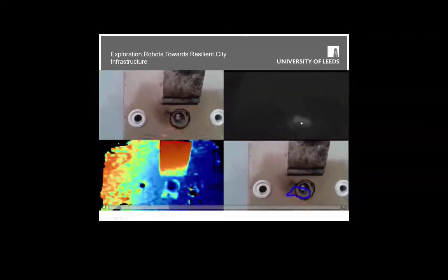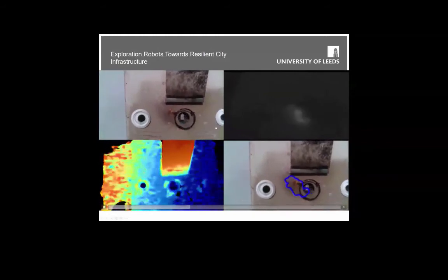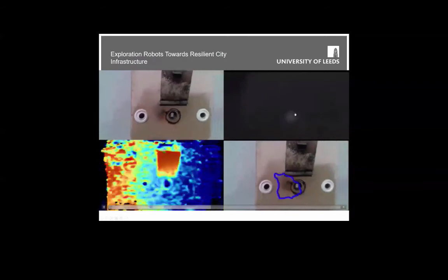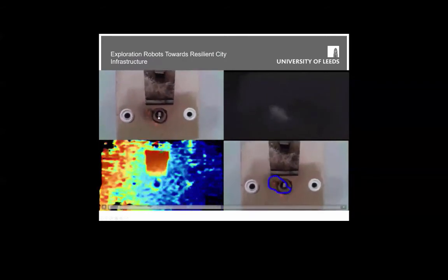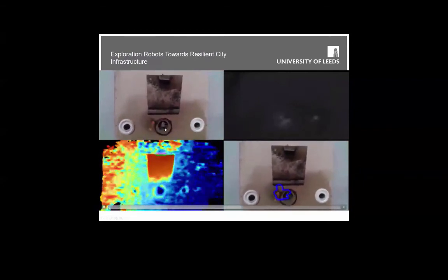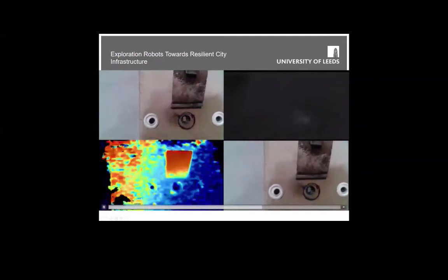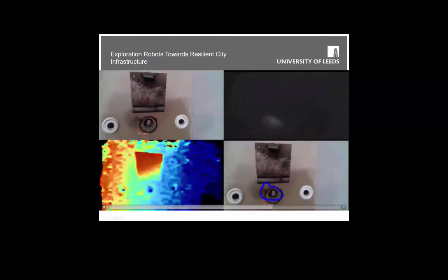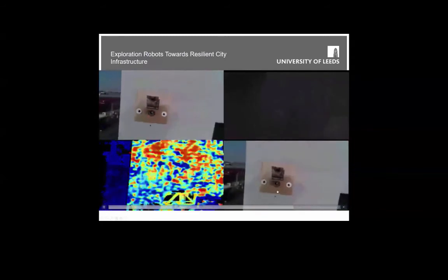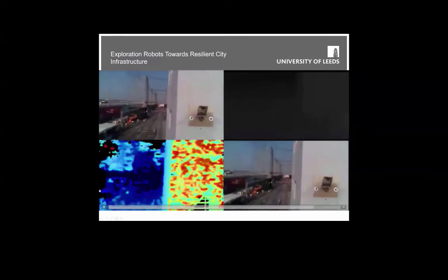One of the things you can see here, this is obviously the thermal view, and this is the camera view, and you can just about see what we're trying to do. This is mapped here, and this is mapped here, and we're trying to fuse these data points together to understand the position of the fire and spray it. This is particularly hard because the flame is blowing in a different direction, and to get points we have to shoot it into a hole. Putting it in a hole was quite a difficult challenge. In the end, we ended up adding offsets so that we could find the right position for spraying it into the hole.